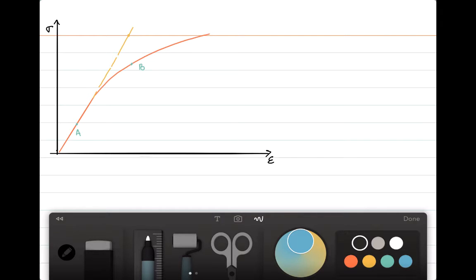Of course, these inputs are given by means of actual mechanical tests that are carried out on the material properties. Now, let's say that we have to trace this particular path for a material. And along this path, you have a certain linear region, which can be clearly seen as a straight line. And I continued that by means of the yellow curve, which is also following the same tangent. And that is for the linear behavior of the material.